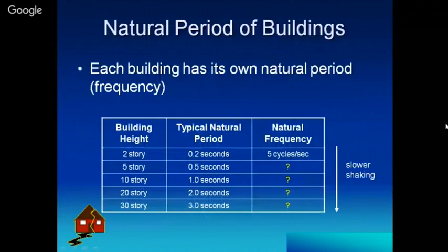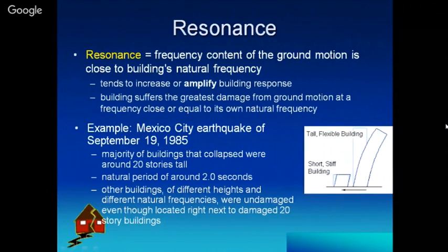As I've shown, you can see that it is a slower shaking. The arrow shows that as the number is increasing, the time period is increasing. Okay. Now again, resonance, that depends upon time period and frequency. Depending upon the natural time period of the building, we have a certain time period and frequency.